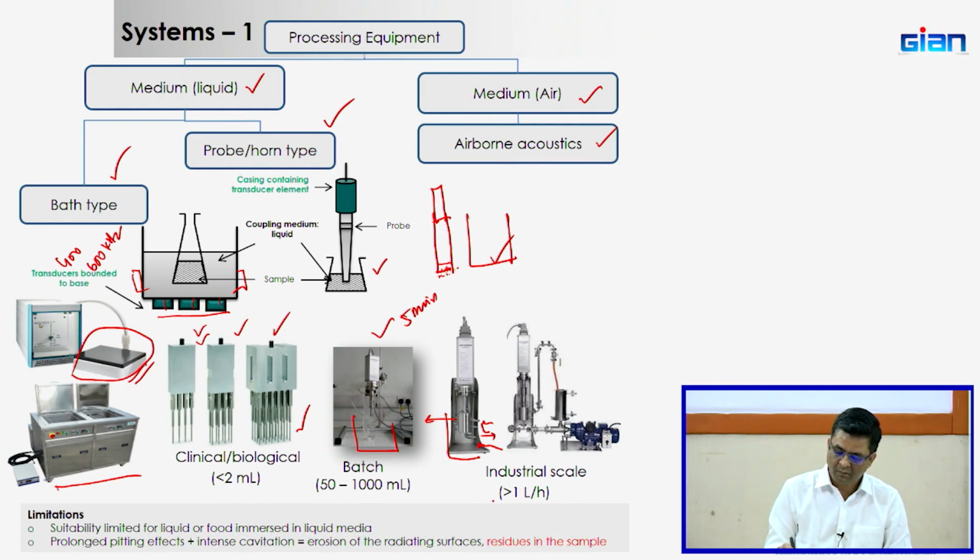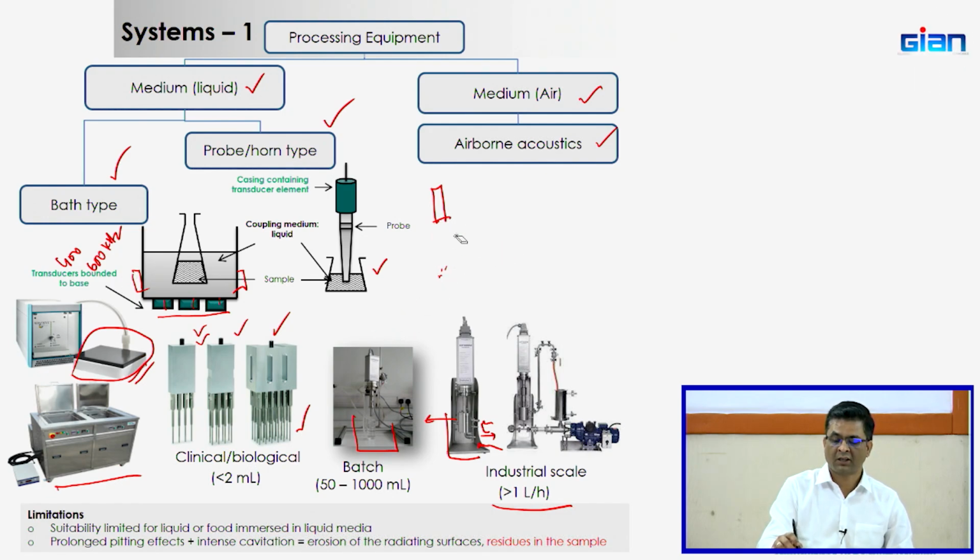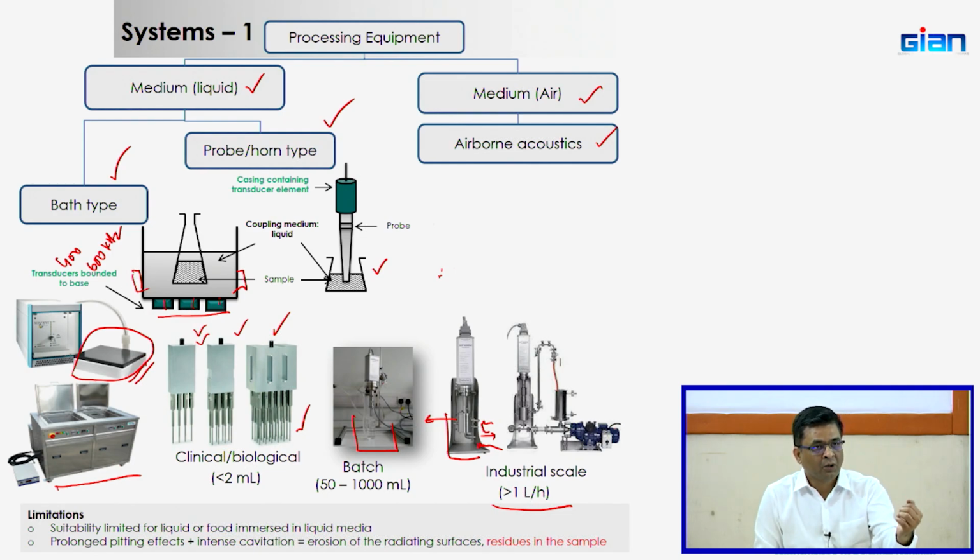Now, if you see here, suitability is limited to liquid or food immersed in liquid medium, because you need to have a liquid there. And one question comes all the time: if we are using ultrasonic all the time, the pitting, that means leaching of material, comes into the liquid food. We carried out that experiment extensively and spoiled almost 10 to 15 different types of probes to see the amount of metal which leaches.